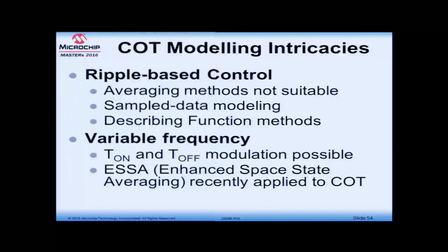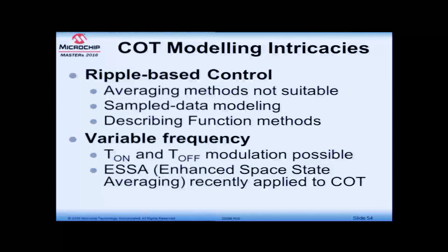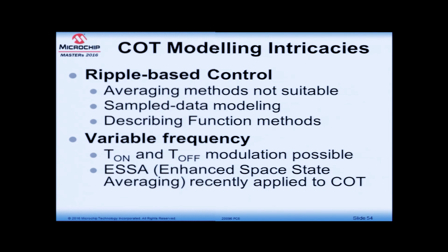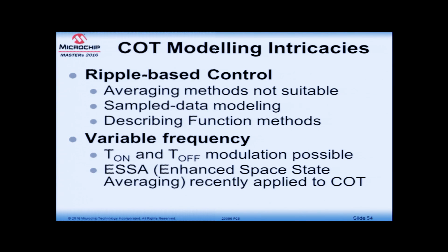You can also look at the constant on time on another side. So you can look at the constant on time control as a variable frequency control, where the off time is being modulated by the controller and the on time is being modulated through the on time generator.